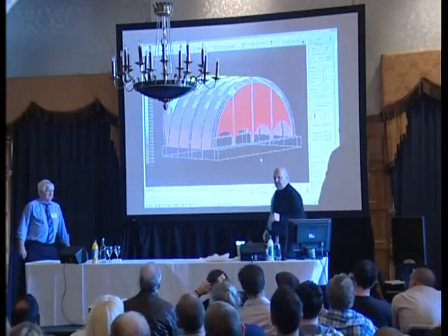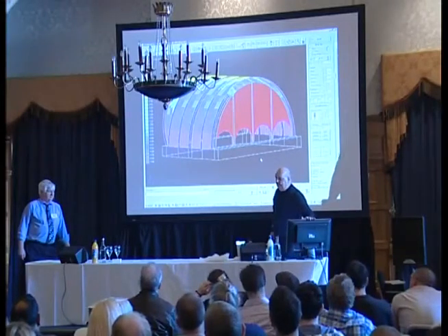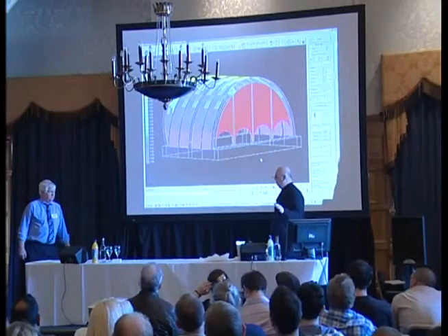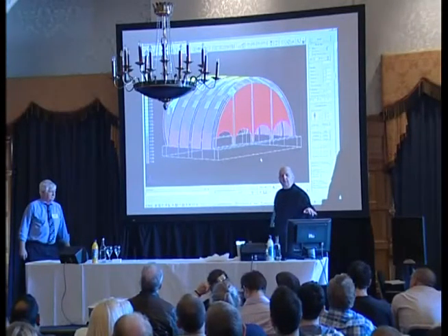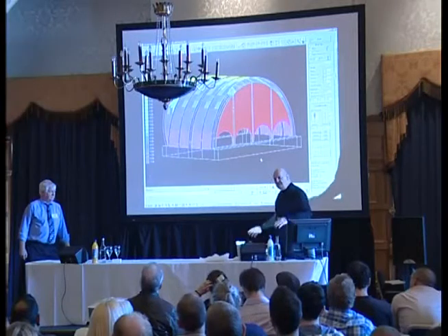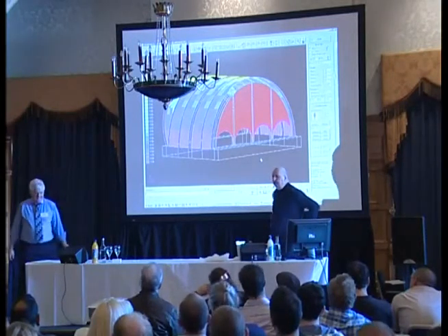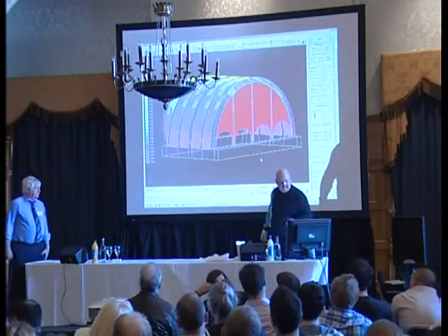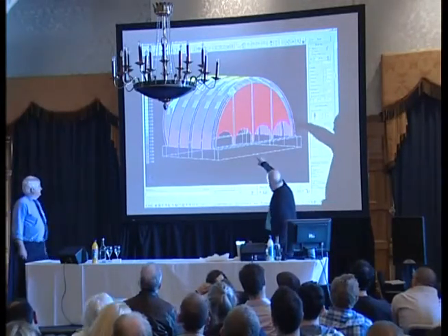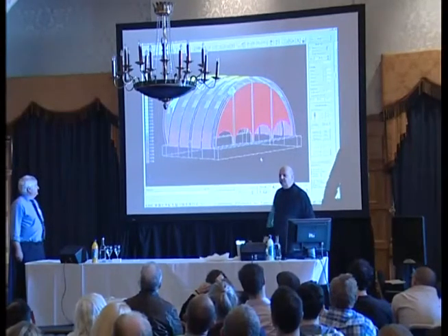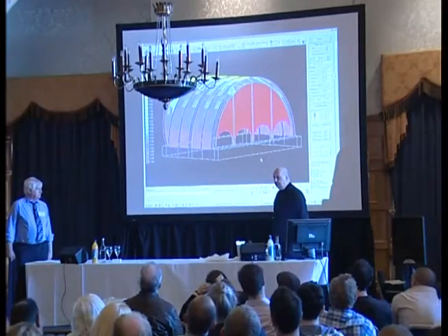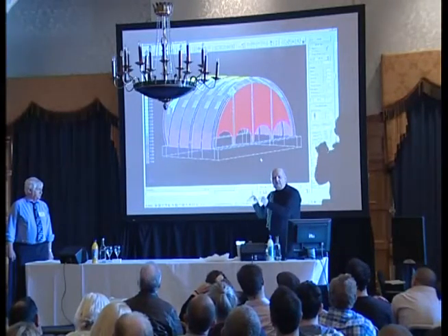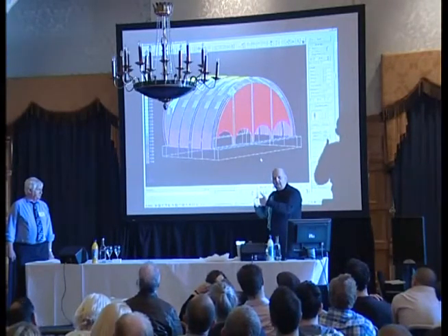We are so committed to this package that we think, we're not sure, but we've been told, that the other people using this are using the American wind codes, which are very similar to our own, by the way. We're not trying to make a big deal of that. But we were so concerned to get accurate figures. If you look, the little patches on there, each one of them is calculated separately from building code. It's not guesswork. It's not our information. It's taken out of a book that says you will apply the pressures like this for that slope, that angle of attack.